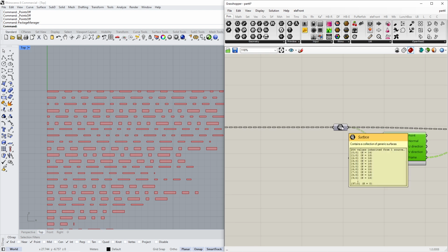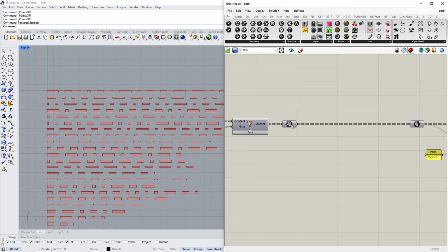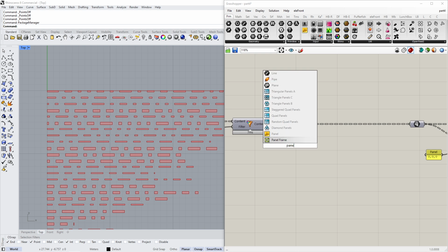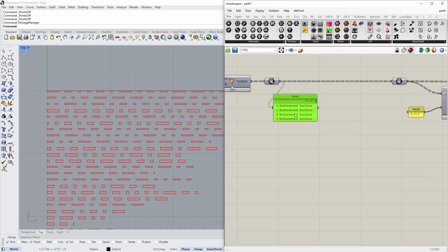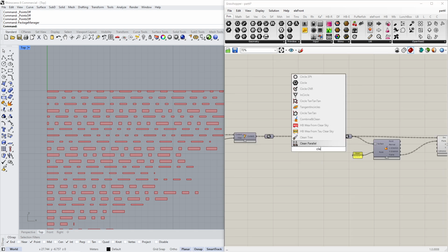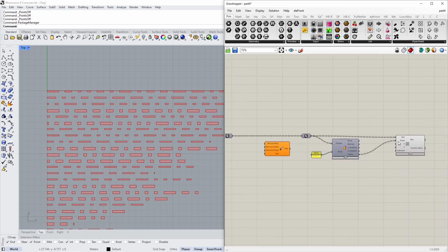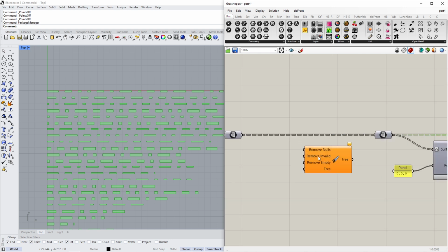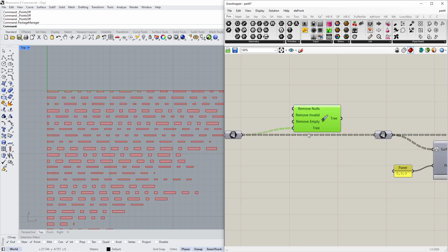The only thing I want to do is, because we have a lot of empty branches, if I can show you, because of course not all surfaces were retrieved. If you scroll all the way down, because there's no dark blue color in the top of the facade, all those branches are empty. So I'm going to clean those out, because this component takes those empty branches into account, so it can give some troubles, right?